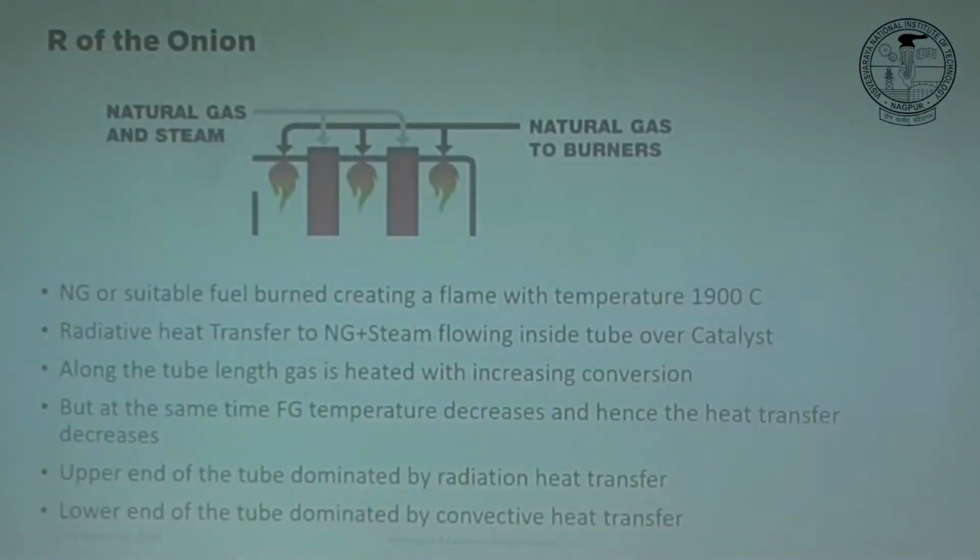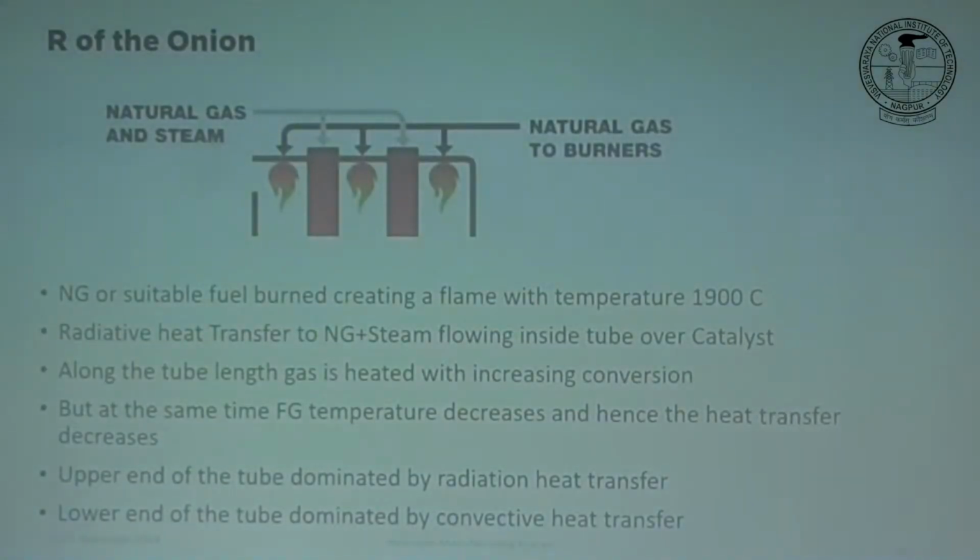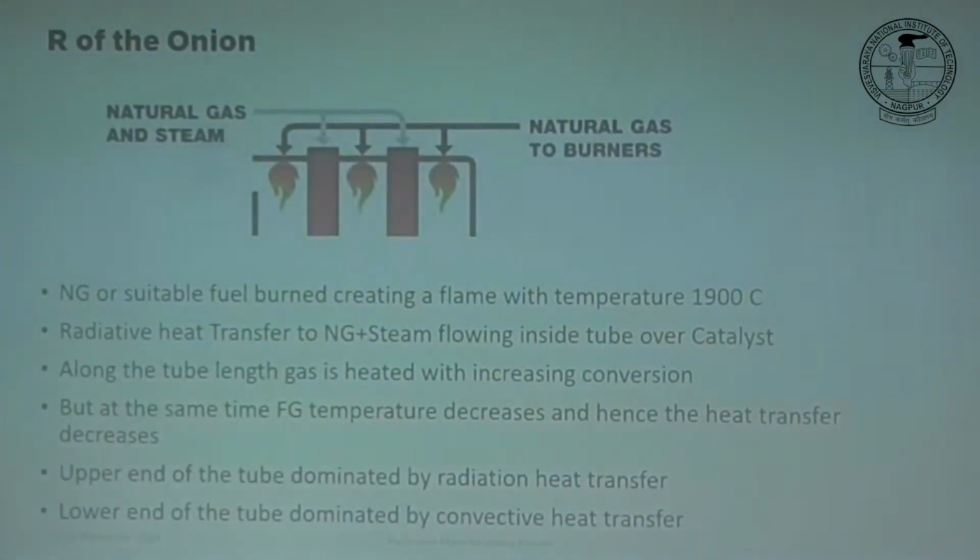And it will start to absorb more heat, because we already said it's an endothermic reaction, so a lot of heat is required for the reaction, right? So what it means, ideally or theoretically, I can put a very long tube, right, and cool the flue gases or the combustion products up to a certain temperature, up to 850 degrees, right?